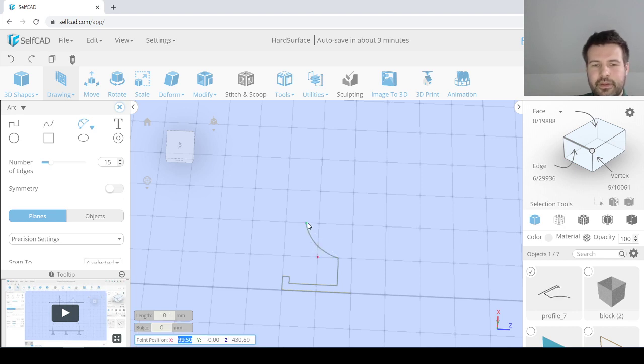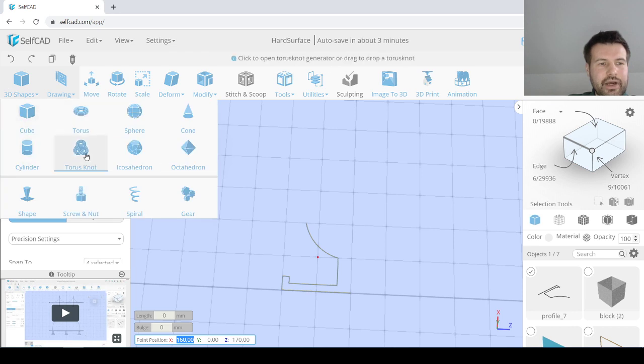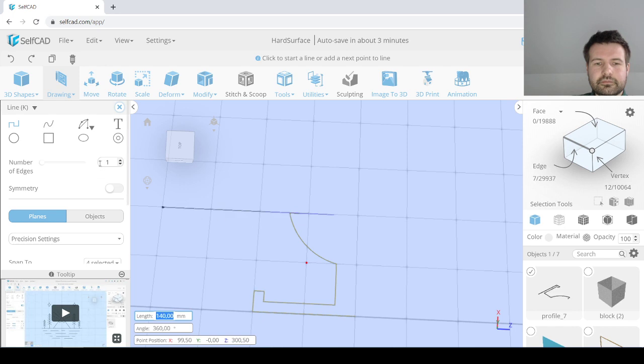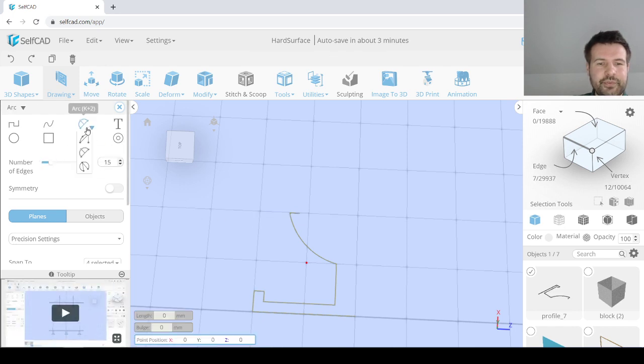So you just take the beginning, make an offset, and move the arc with the bulge factor in this direction. Now I need to add some thickness to the first part of it, and basically just repeat the 2-point arc on the second level. I also need to add the same offset here, but if I do it this way, it might not be exactly perfect, but I think we can use it this way.